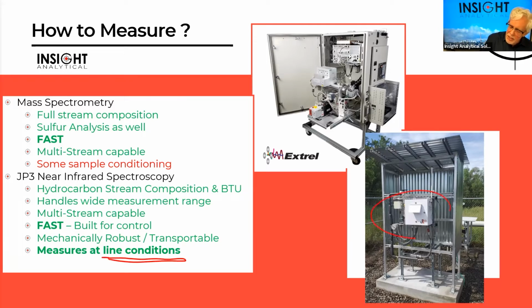Spectroscopy. One of the things I'm going to focus on today is the use of near-infrared spectroscopy to do these kinds of measurements. We can do a complete hydrocarbon stream composition and BTU analysis in real time, fast, built for process control, handling very wide measurement ranges and big changes in compositions.